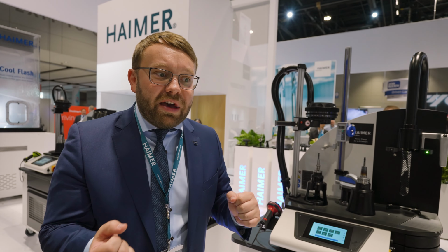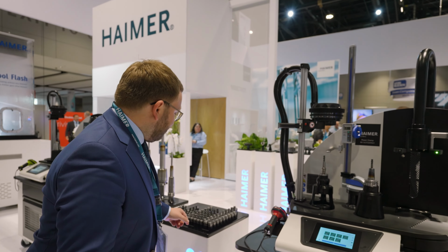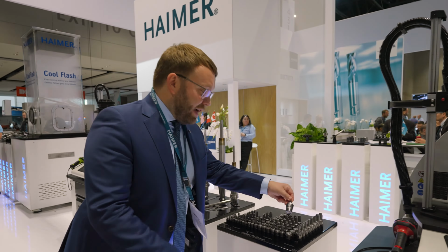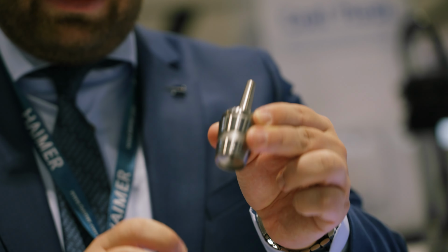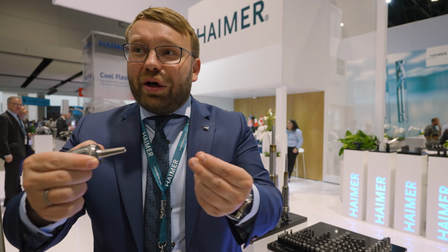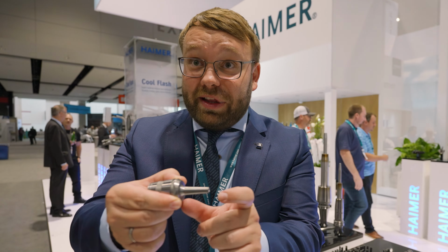Boom. Speaking more about Shrinkfit, now we have customers out there using Shrinkfit for milling machines, 5-axis machining. They can also use it for lathe. I mean, look at these kind of collets, shrinking collets. You can put it on driven tools, on any kind of ER, call it outer diameter basically. And the beauty of it is you don't have to interrupt the cut. So if in your lathe you have a regular ER collet, you take out the cutting tool, then you have to insert the cutting tool, you have to guesswork the edge, the length of it.